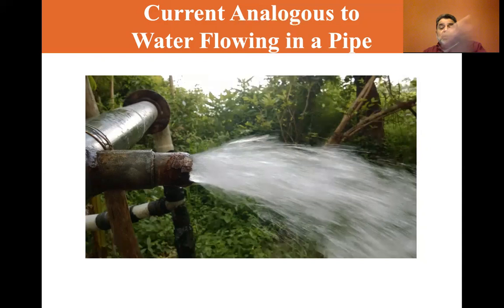Now, if you were to put those one after the other, the large fireman's hose, then the garden hose, then the little Tygon tubing, they would all be limited by the Tygon tubing. No matter how much pressure you put in the fireman's hose, it's going to be regulated by the small Tygon tubing, and that would be these three hoses in series.